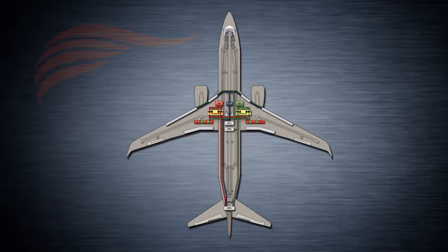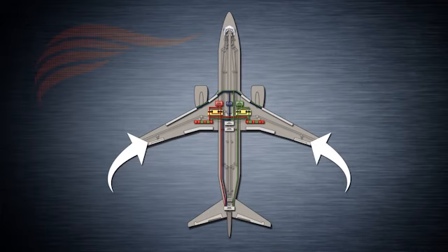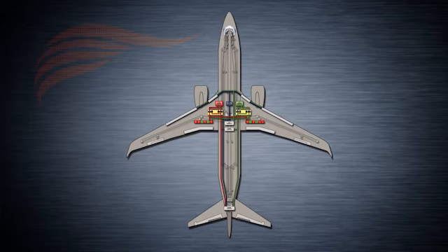Ailerons are movable surfaces on both wing outboard trailing edges that control the flight attitude of the aircraft about the longitudinal axis, more commonly known as roll. The ailerons are coupled so that when one of them moves down, the other moves up. There are 3 ways of achieving roll control on the 737NG. Manually, by moving either control wheel; automatically, by autopilot input to move control wheels with actuators; or through flight spoilers. These will be discussed at a further stage during this lesson.